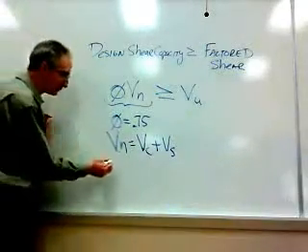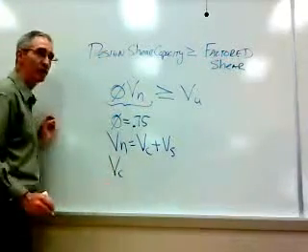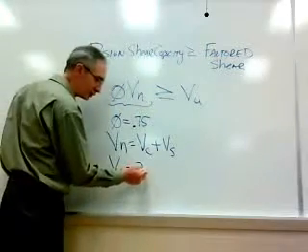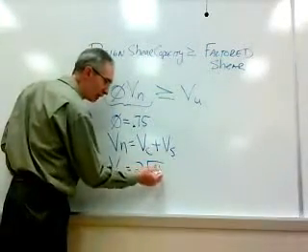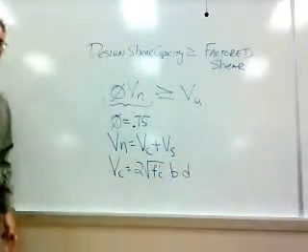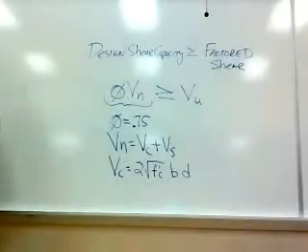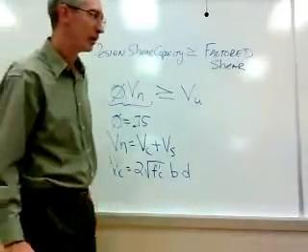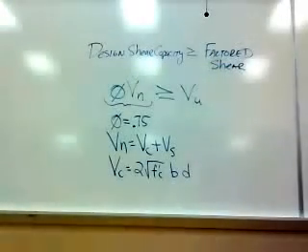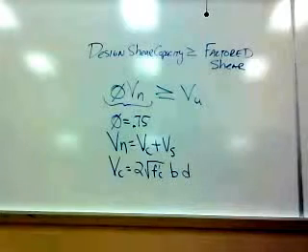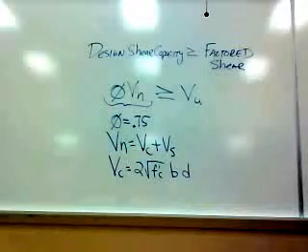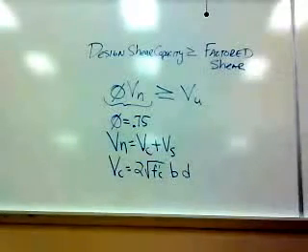For the concrete, we're just going to give you one formula. The formula for the concrete is 2 square root of f prime c times b times d. They call this the conservative formula for V sub C. There's another formula that you can use that's much longer and much more exact, but for our purposes, we'll always use this one. Okay?